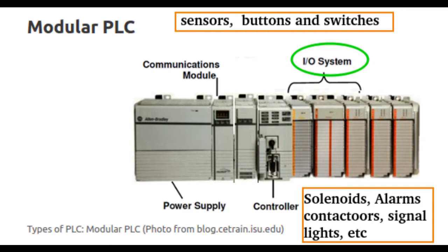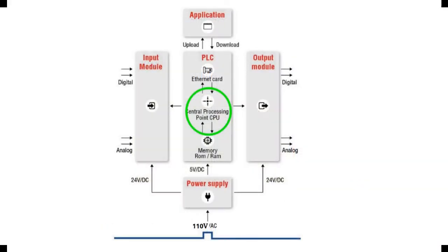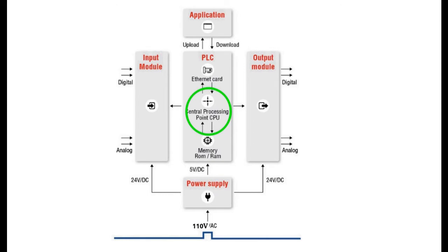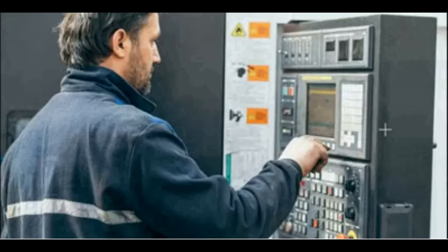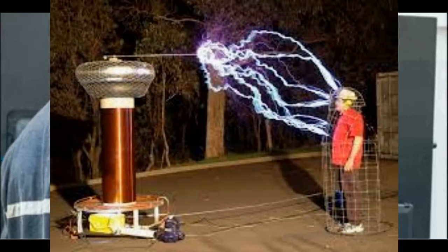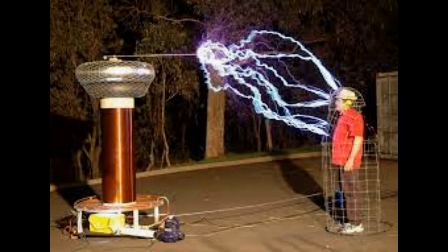ensure that the power supply is doing its job. A 24-volt power supply needs to provide 24 volts, not 21, not 22, not 20. Electrical noise and interference is a big problem, so keeping the equipment close is very important, as this will help to create that Faraday cage to protect the internal components.